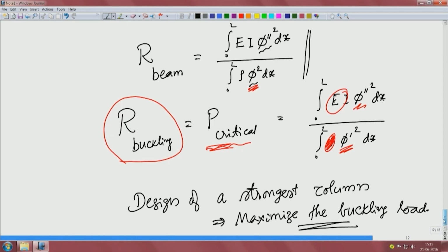So, the highlights of what we have discussed today is that, starting from Hamilton's principle, we can write the equation of motion for elastic systems that are vibrating under no external force, that is free vibrations, okay. And then we got an eigenvalue problem, where we have eigenvalues and then eigenfunctions. We solved the eigen equation by assuming separation of variables, that is the space, the x variable dependence, and time we separated out like phi of x times q of t.